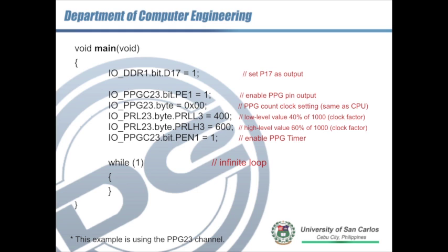Now adjusting the duty cycle does not change the frequency, but rather adjusts the amplitude, or the magnitude, of the sound. So if you go for, let's say, 90% or 100%, of course the sound would be much louder than the sound produced below 50%.